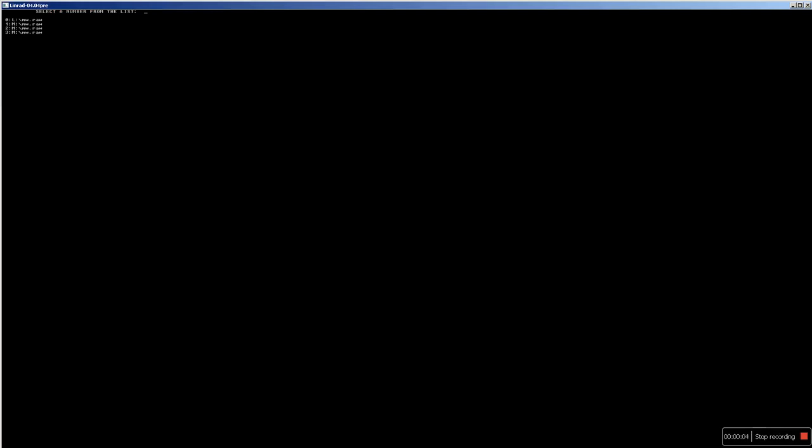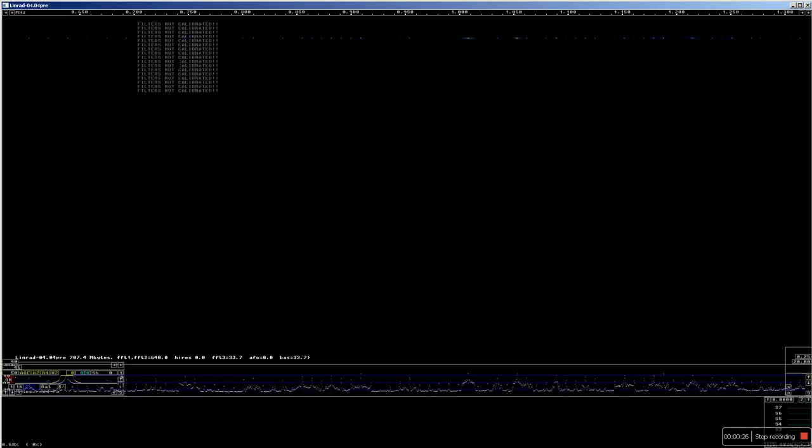And here I press 2 to run Linrad from the solid state disk M:, but with a new set of parameters. So 2, enter. And I want the AM mode, that's F of course. Run repeat recording endlessly, yes. So here we are. Now the parameters are new, so I have to rearrange the screen a little bit.